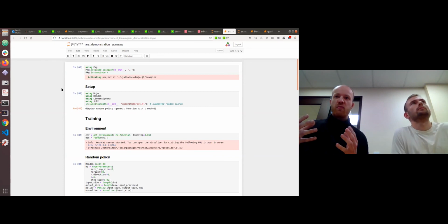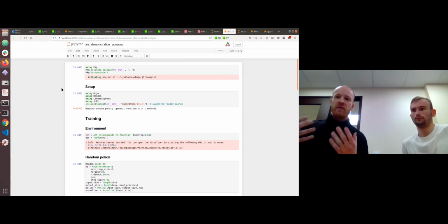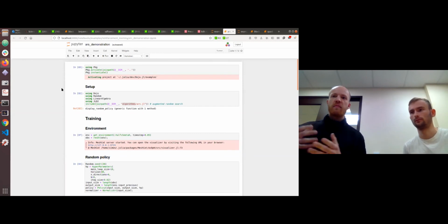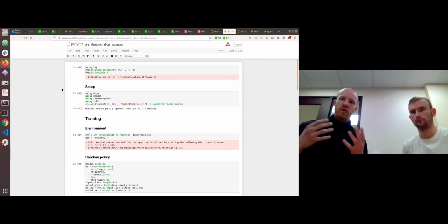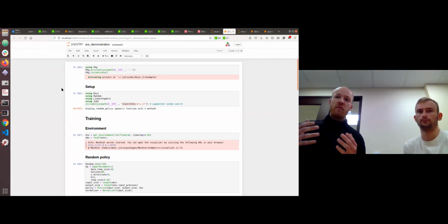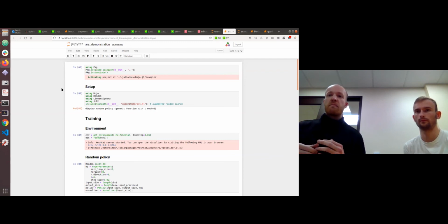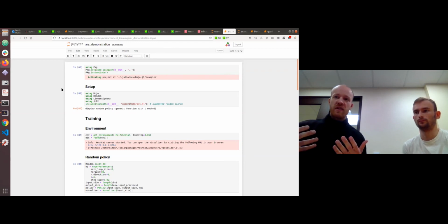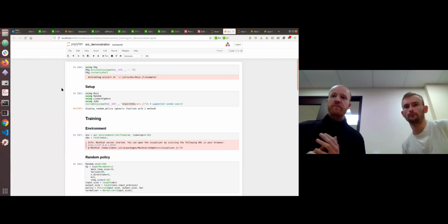Intuitively, MuJoCo is a primal method, and that's part of the reason why their soft contact model can't really converge to hard contact, because the problem gets ill-conditioned. What we're doing, and what the Mehrotra predictor corrector algorithm is doing, is a primal dual approach, which means the problem is better conditioned. That doesn't mean the linear system isn't ill-conditioned, it is. But in practice, this is part of the beauty of interior point methods: they can still be reliably solved to really good tolerances.